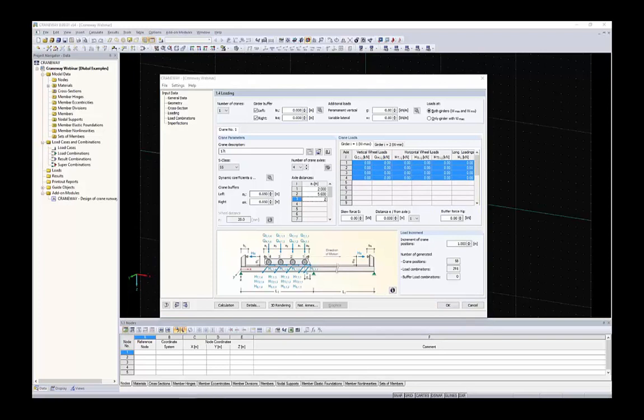So I will just copy the loads from this sheet by selecting all the cells, and Control V, paste the loads over there. We have a minimum load on the girder 2, because I want to design both girders. And we also have an additional skew force, minus 20.1. Okay.